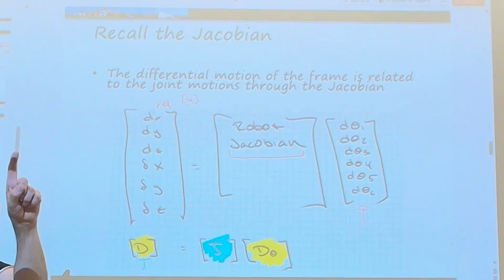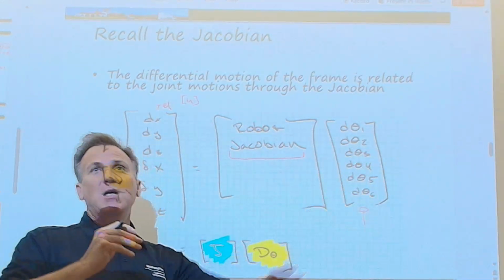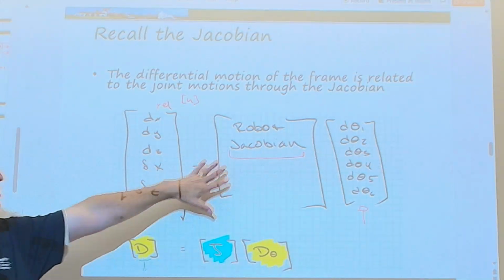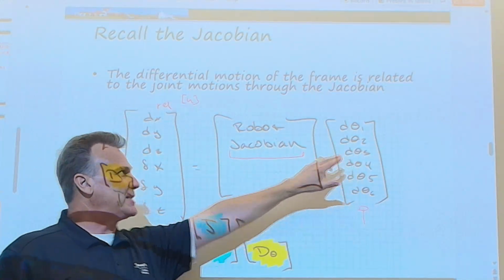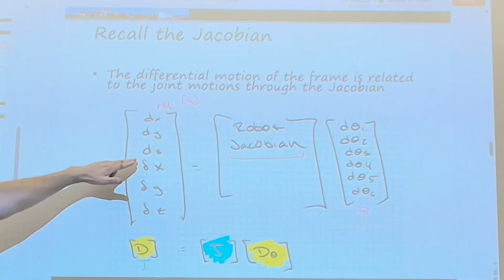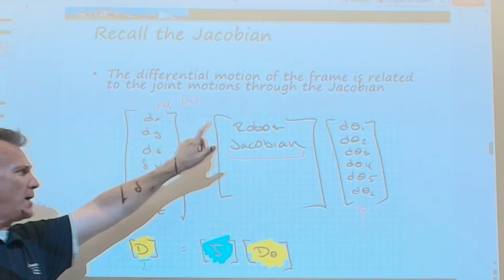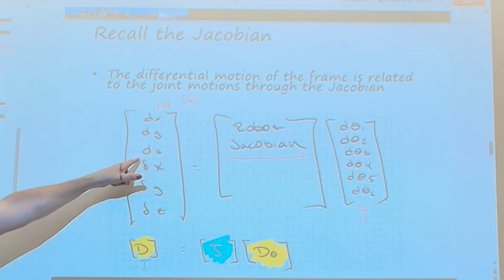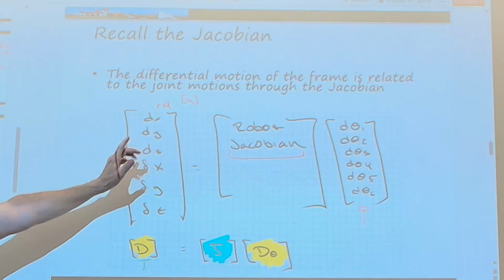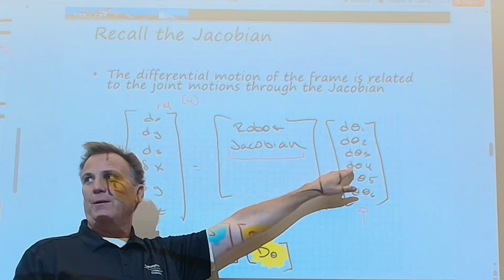No. Because I'm going to have all these other little delta theta 4, right? So it's going to get theta 4 to where it needs to go. But in the process of doing that, because I have this Jacobian, it's not a 100% linear relationship to this guy, because I have all these sines and cosines potentially in through the rotations. Then what's going to happen is that's not where it's going to be, because these velocities all changed. So this is linearly changing, but this is not. So that position could be something completely different. So I can have a position error here, but I'm position correct here.